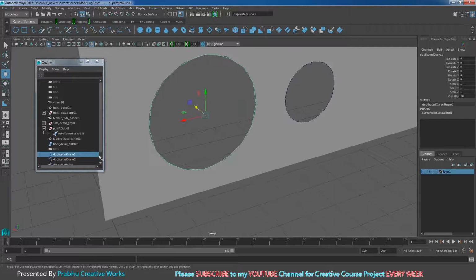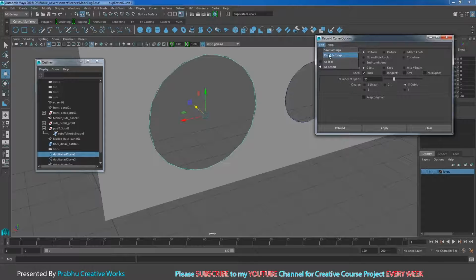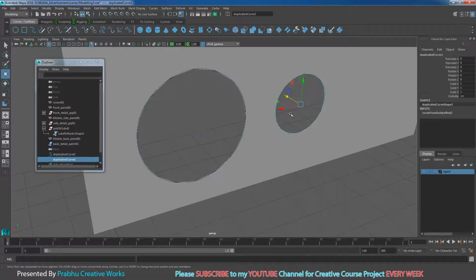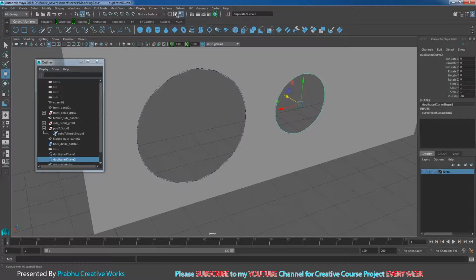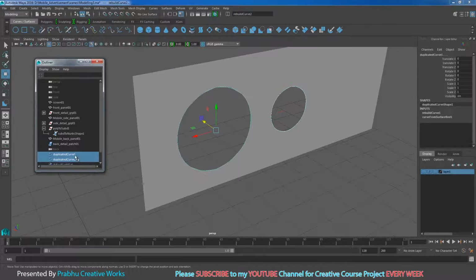Here you need to rebuild this curve. With the duplicated curve selected, go to curves and choose rebuild option box. Here you want to reset the settings, set the number of spans to 20, choose 3 cubic and choose rebuild, so it will be rebuilt perfectly. You want to do the same thing on this one: select this curve, go to curves and choose rebuild option box. I will reset my settings, give 20 divisions and choose rebuild.